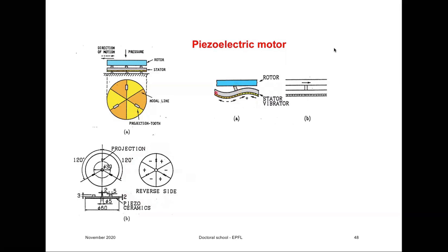And so your piezoelectric material and whatever is glued on the top of it would make this motion, and then whatever is on the top and supported by these legs will rotate. There would be a standing wave, and it would rotate, and you can change the direction of this rotation.